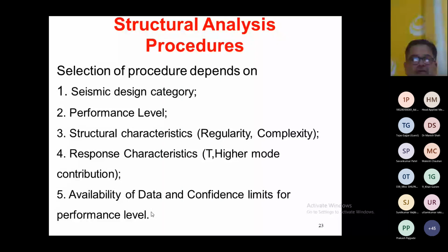Structural characteristics: whether your structure is regular or complex, right? Suppose your structure is irregular, in that case definitely dynamic analysis is preferred. The response characteristics: sometimes if you're talking about tall structures, in case of tall structures the higher modes may contribute. In that case also dynamic analysis is preferable. Availability of data and the confidence limits for the performance level, right? So these are some of the factors.